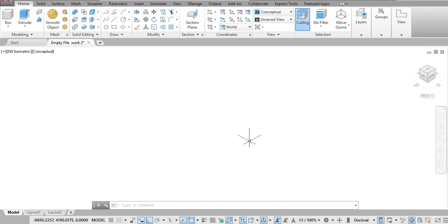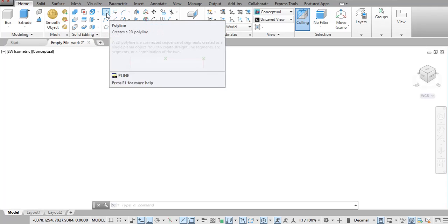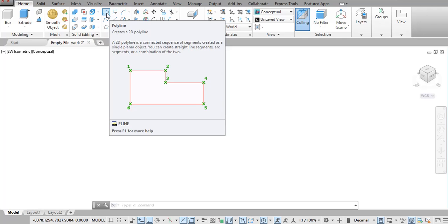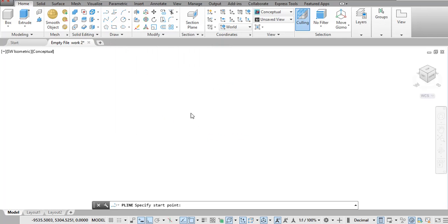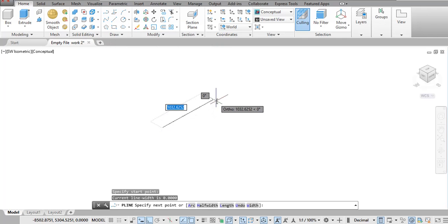So we start in these very good terms. Now we have our AutoCAD 3D already launched. We want to produce the model of our walling unit, that is our block. We can pick our polyline. The length of the block is 450. You type 450, you enter.